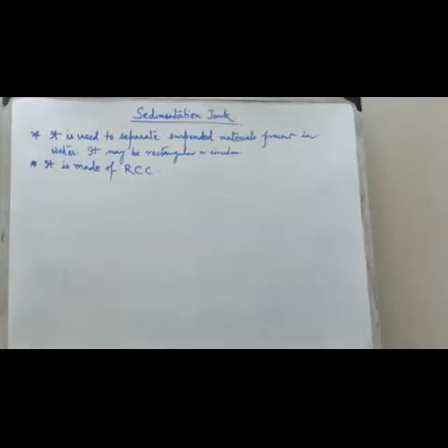Now, rectangular tanks with horizontal flow are generally preferred to circular tanks with horizontal, radial or spiral flow, because this type of sedimentation tank is more efficient and can remove as much as 70% of the suspended impurities present in the water.